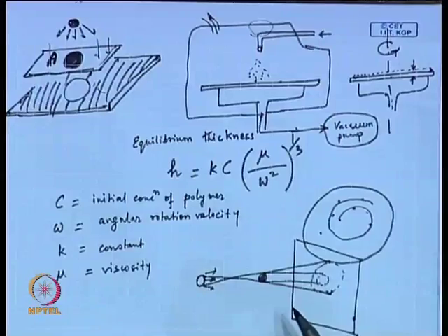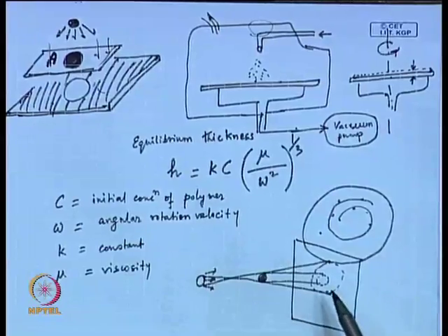So, once you are talking about this shadow and the light source, you will have this problem. What you end up with is basically half light around the object. You have defined the object very well, but around the object you will have something called a half light. So, this is called the half light effect during exposure.